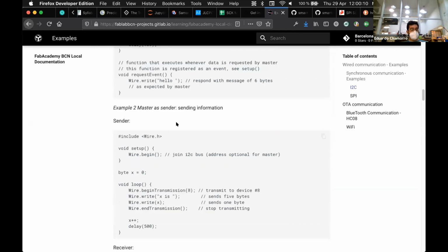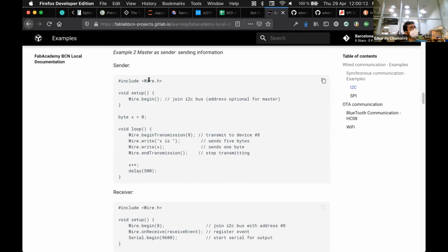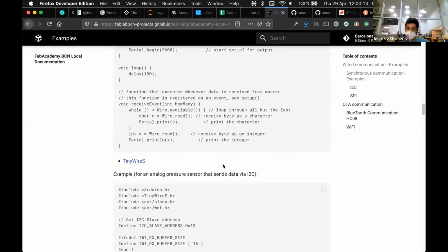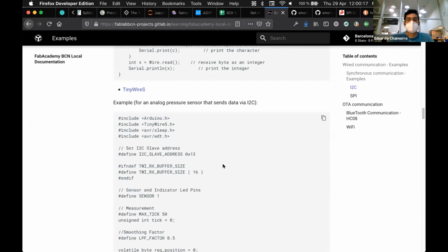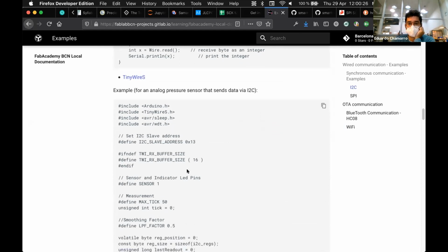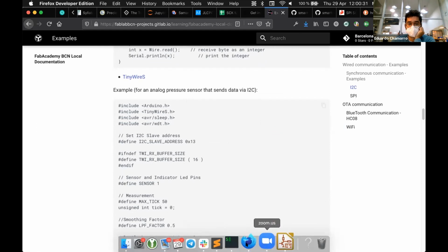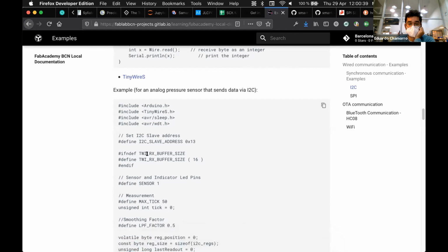Talking about libraries, we talked about Wire yesterday. If you're using ATtinies, especially because of memory size, there's TinyWireS and TinyWireM for slave and master. They're going to have to change the name too. They are done like that because ATtinies don't have I2C in hardware. Some of them have to define this protocol that is called two-wire interface.